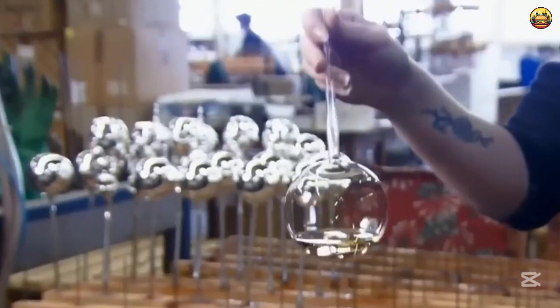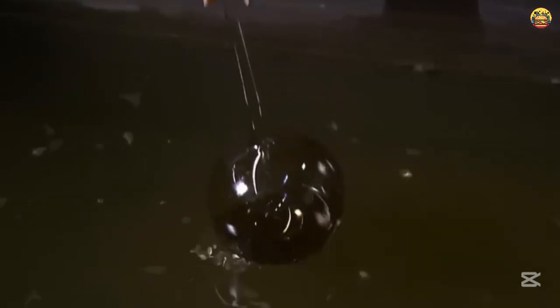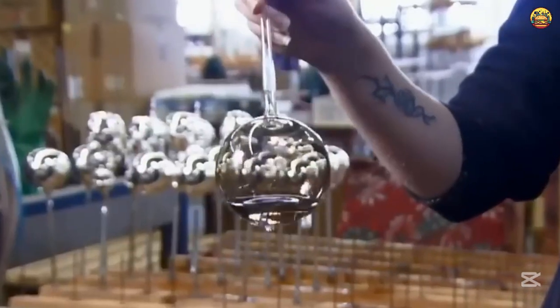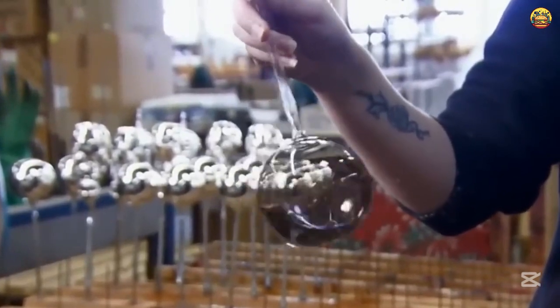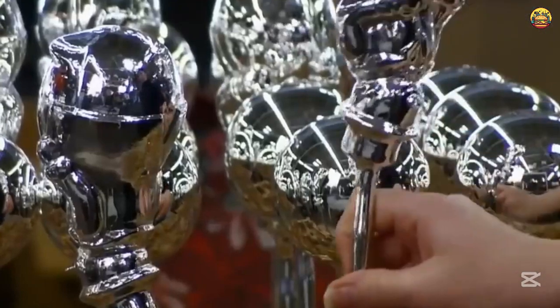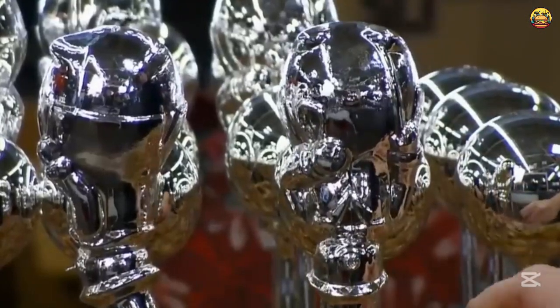After shaping, the glass blanks are coated with a silver layer to give them a brilliant shine. This process uses a solution of silver nitrate. The interior of the bauble is filled with the solution and heated to around 176 degrees Fahrenheit. This causes the walls of the ornament to be coated with a thin layer of silver. Producing a batch of 50 ornaments requires approximately 1 gallon of solution.